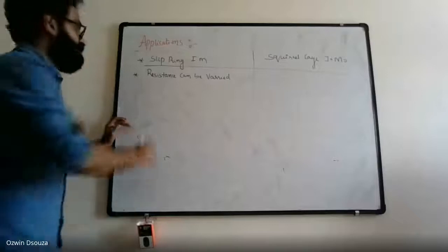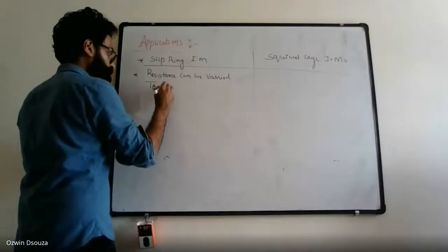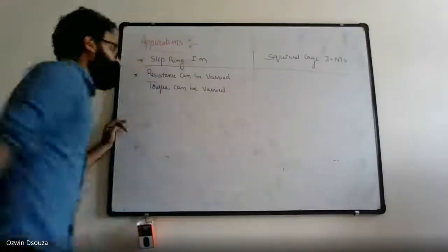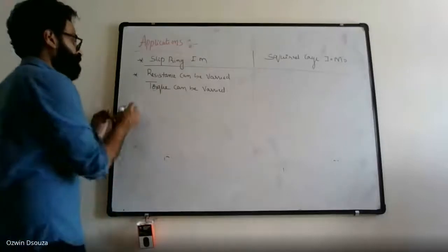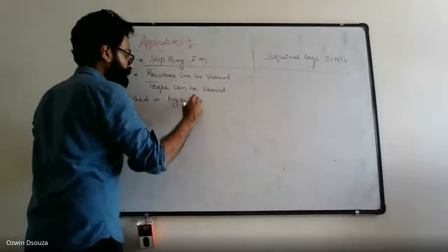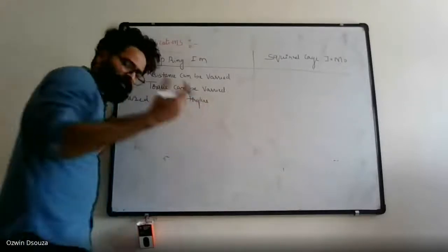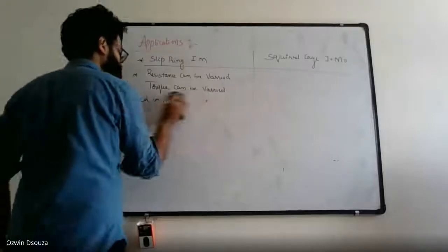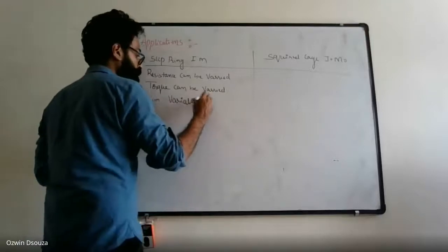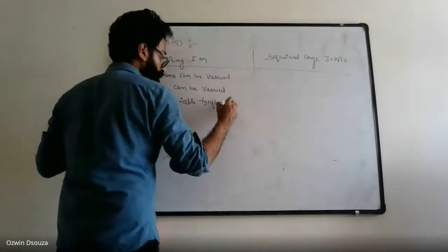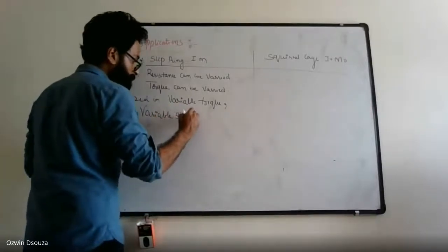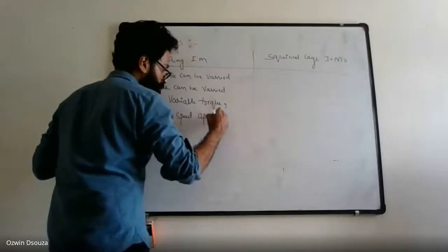Since you can vary the resistance, torque can be varied. Hence, they are used in high torque. Instead of high torque, you can say variable torque, that sounds better. So they can be used in variable torque, variable speed applications.